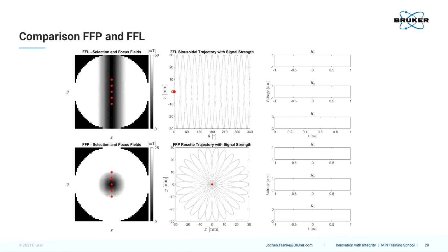And what we can also see, if all the points are hit by the field free line simultaneously, which in this case was at 50 milliseconds, we have the highest peak in the response. That's because we are acquiring all the particles along the integral of this field free line, which does not hold for the field free point, as we do not see all the points at the very same time. This is why FFL is said to be more sensitive for non-sparse objects. Okay. All right.